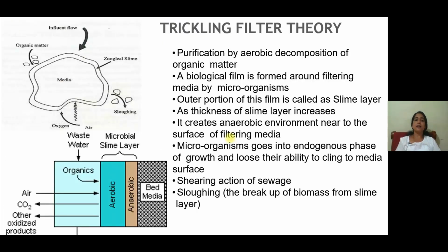And the theory of trickling filter: the purification happens on the basis of aerobic decomposition of organic matter. Here you can see a pictorial representation. The wastewater contains organic matter, and in the first filtration phase it undergoes aerobic decomposition, and in the second phase it undergoes anaerobic decomposition in the filter media.